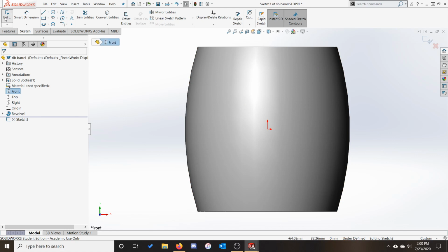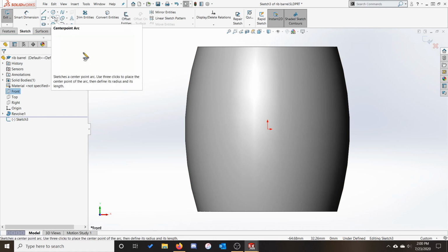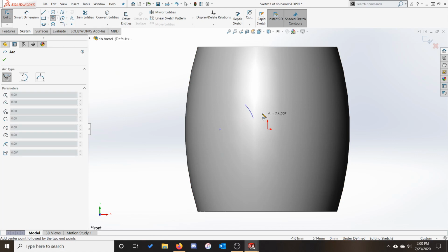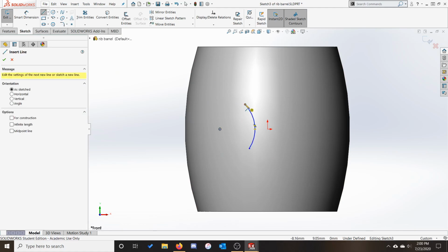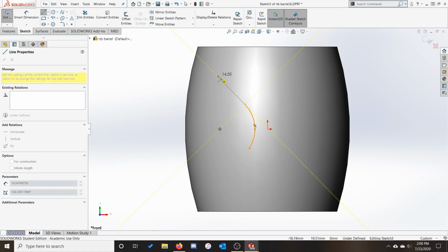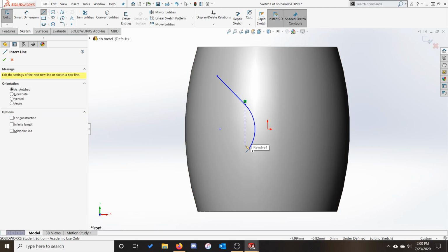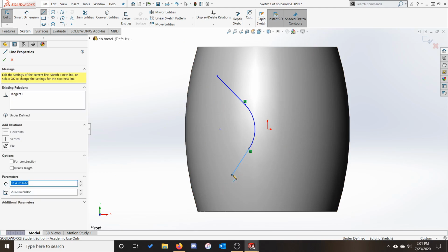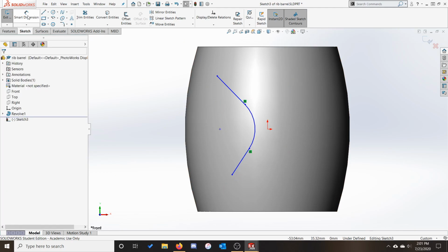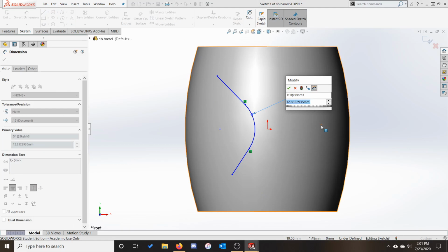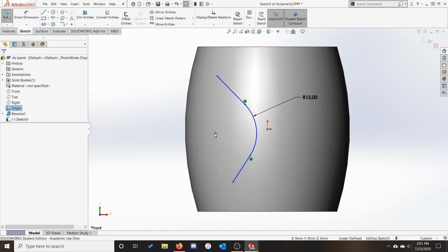On our right plane, we can draw a sketch that would look similar to what we would use to produce an extrude. However, we can leave it open along the edge where it would interface with the object. I personally tend to prefer leaving it so that the endpoints fully connect in with the object's geometry, but they can still technically be left unconnected if that proves difficult. The same definition rules apply that we listed earlier, so we need to make sure that all of our edges are properly located within the geometry, and that the endpoints of our arcs are properly defined.